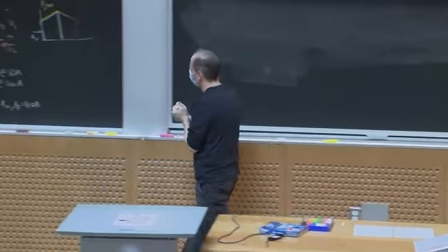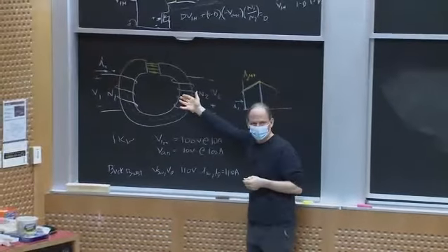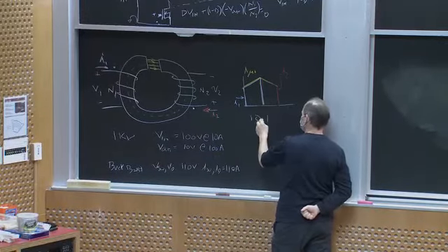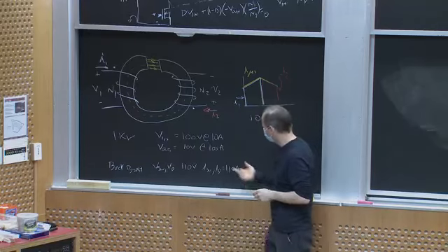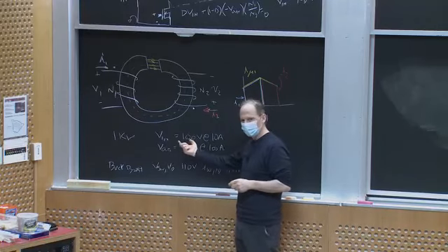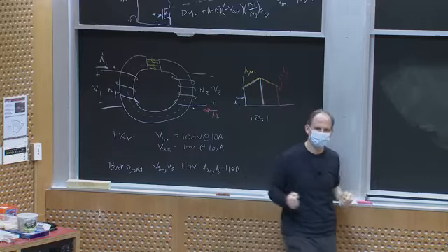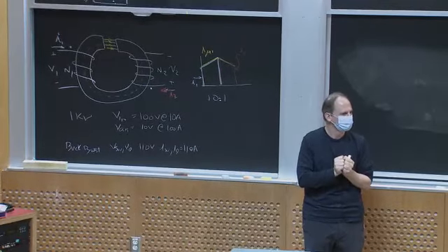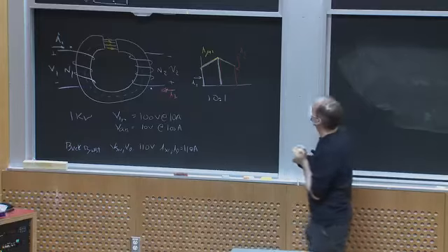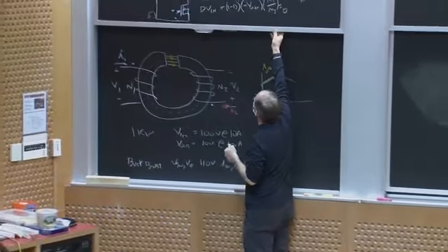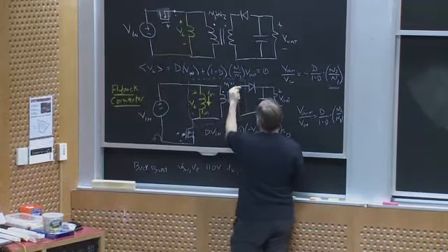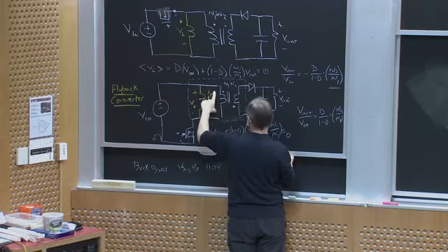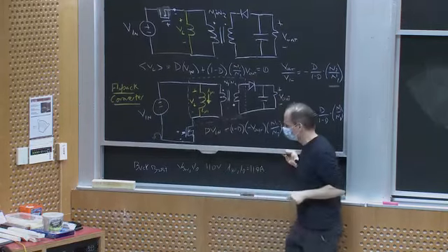On the other hand, suppose I designed a flyback and I used a 10-to-1 transformer. Okay, so I'm going to get my scaling, instead of just by using some extreme duty ratio, by putting it into the turns ratio. Okay, what does the turns ratio do? That rescales the high current seen at the secondary to the low current at the primary, and the high voltage at the primary seen as a low voltage at the secondary.